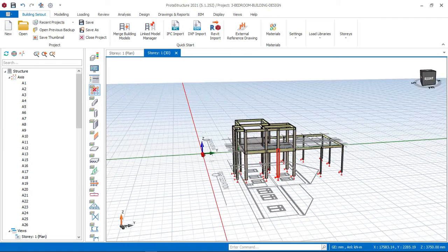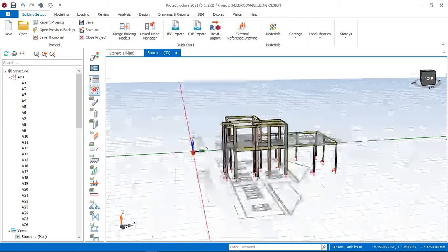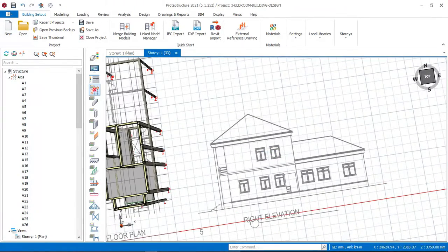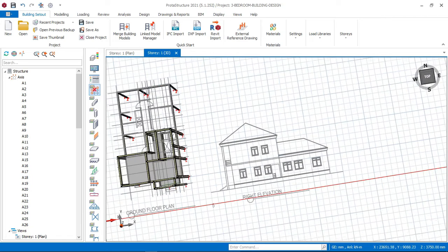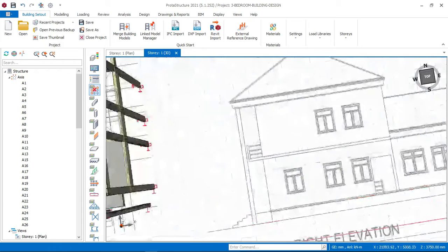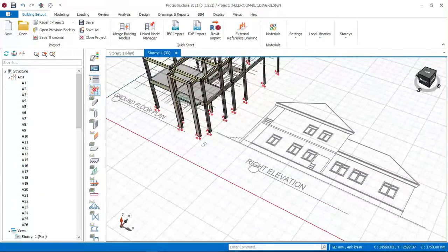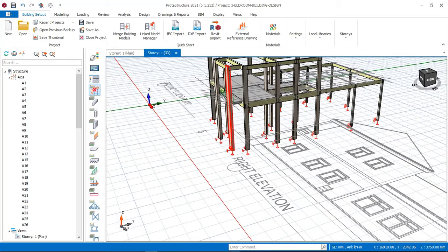If you see this very shape here right now, this level stops at this very level, and you can see it also here that this is the level that stops there. You can see that this level stops here, while this place goes up, as you can see, and we have a cantilever slab, and this column is a standalone column which is called a slender column. From the top down to the foundation, it doesn't have a connection between the beam and the column itself. So that is what we have also achieved here. As you can see, there is no connection between the column.